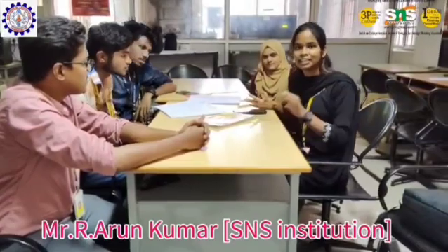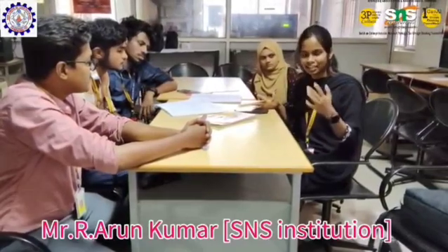So here we can take three cases. As per the hexagon rule, there will be three cases using the front view and the top view. In the first case, the hexagon plate will be parallel to HP. In the second case, the hexagon plane will be perpendicular to the HP and parallel to the VP. And the third case will be inclined. So now we are going to see the case that was inclined.